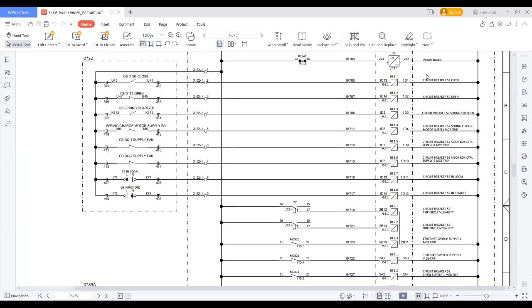So how will he get this indication? He has to integrate this connection with the breaker connections. So this is the block. You can see 52, which represents the breaker. So to prepare this scheme drawing, what do we require? We require breaker, isolator, CTs, PTs, manufacturer drawings.